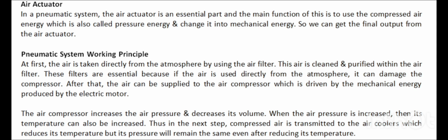In simple words, I explain to you about actuator. So actuator is a device which works upon pneumatic air pressure. If we supply air from A, the plate goes to the upper side, and if we supply air from B, then the plate moves to the lower side. In this way we convert pneumatic energy into mechanical energy.